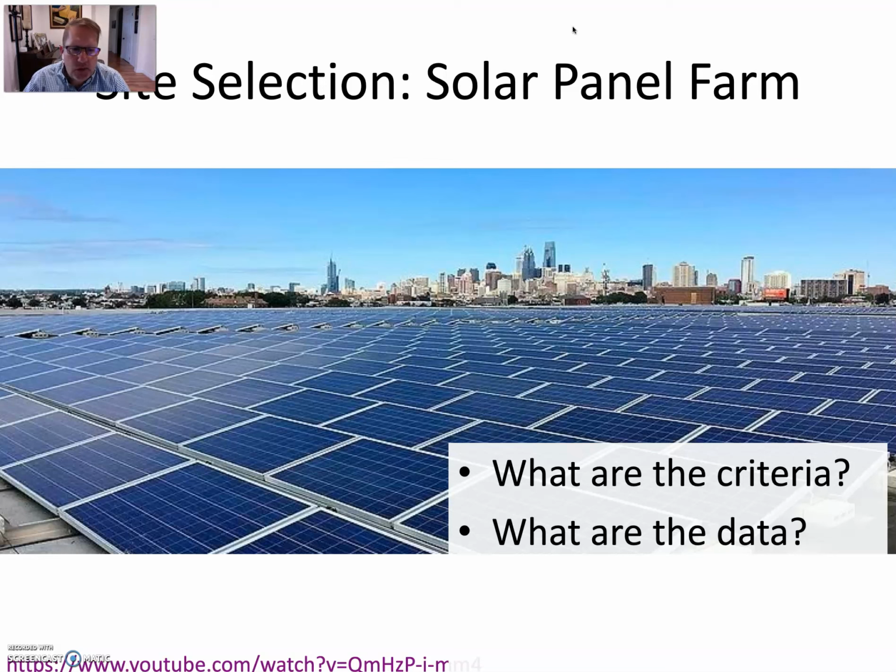What are the data that would be needed? So if those are the criteria, then you're going to need terrain. We're looking probably for flat areas. You're going to need roads, cities, you're going to need rivers. For the terrain thing, we haven't done any raster analysis in this class, so don't worry about downloading digital elevation model data. But what you might do is just explore online areas that appear flat and find those areas that are flatter in the county that you choose. And then you could draw a polygon around the flatter areas and have that be an area that you know is fairly flat. Unfortunately, since we're working in Utah, it's quite easy to find flat areas of land.